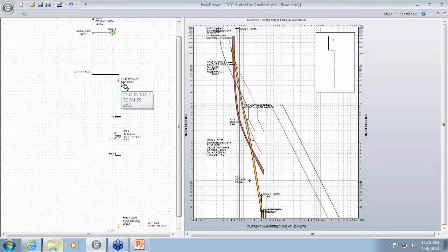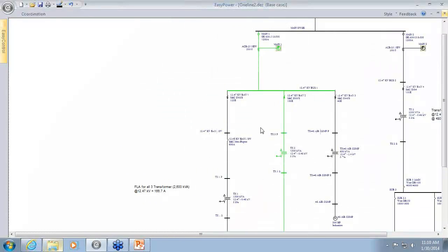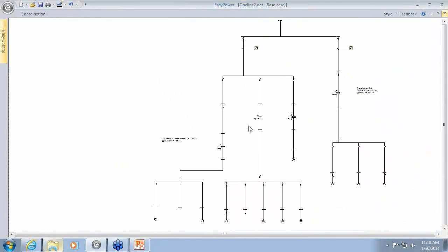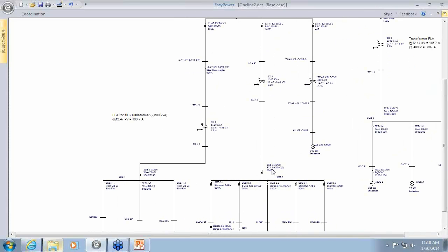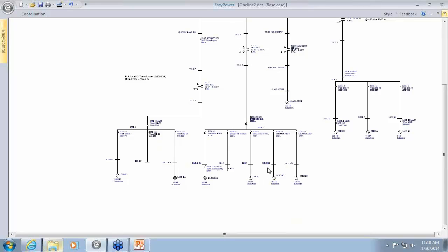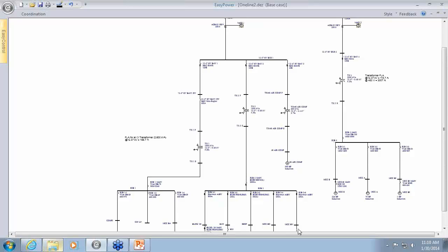with the instantaneous trip, which significantly reduced it from the 54. The other switchgear was reduced as well. But they also know that it does come with additional risk: if, during that maintenance, when the relay is in maintenance mode, they have a fault on this switchgear while they're working and this relay does trip, it's taking off a larger portion of their system.